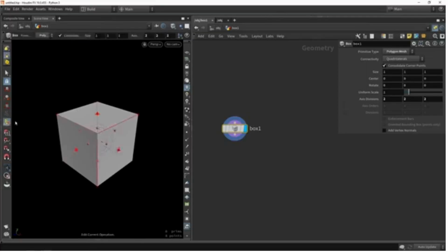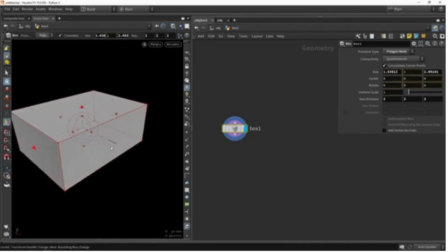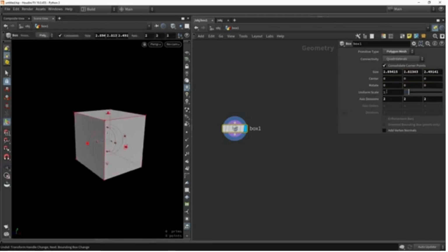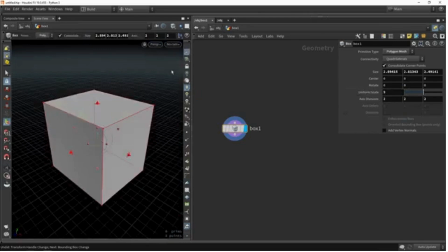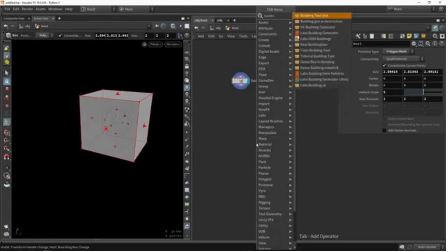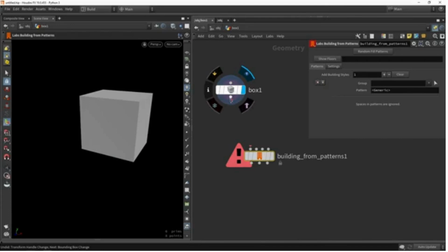An example of a procedural workflow, I'm just going to give you a very simple scenario, is generating a procedural building. One, you create a basic shape, using a box node to define the basic building dimensions. Two, you add details, using nodes like poly extrude to create windows or facades. Three, you randomize variations, which is adding attributes, heights and widths, and manipulating them using VEX code or procedural tools like attribute randomize. Four, you generate instances, using copy to points to scatter multiple variations across the grid. Then you finalize by adding shaders, materials, and lights procedurally using VOPs or predefined tools.